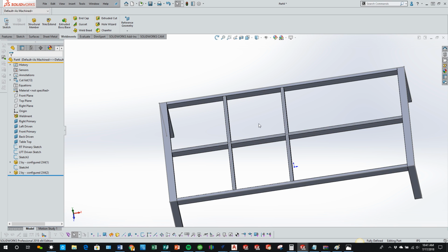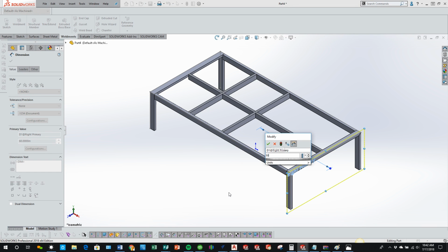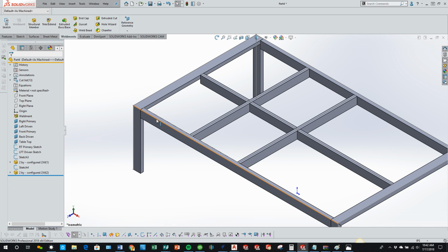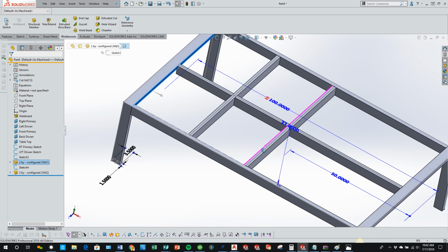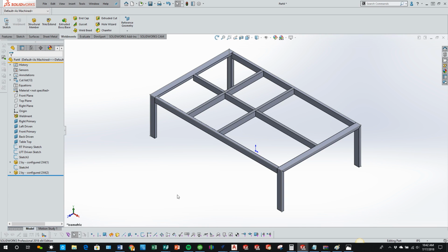Now, once again, I'm just showing you guys techniques of utilizing planes on here. Just wanted to show you how I use them to make my weldments. And so if I came in here and said, all right, I don't need this to be 120 inches overall anymore, let's bump it down so it's at 100. Because I did that construction line coming across here and I said make that always centered, and this line is always coming off center from this point to here, this is always going to update, so it's going to bisect from between this face and this line. Okay, always will do that for me.